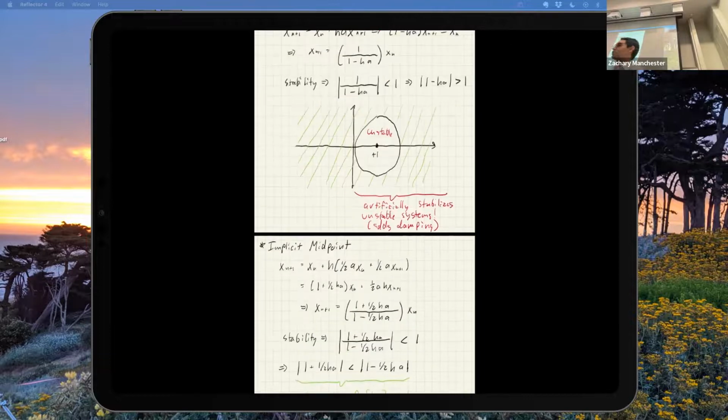Because it's always stable and it stabilizes a bunch of that other stuff. It basically adds lots of artificial damping and is super stable and doesn't blow up. So people like it because it's not going to blow up. If you're trying to make a simulator for someone to just throw a URDF model in and use, you don't want to have the user fiddle around with step sizes and all this stuff to make it not blow up and look stupid.